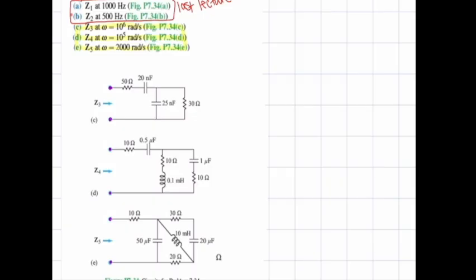Oh, okay. And in this case, your sources have to have the same frequency. They can have phase shifts on them, so they can be phase shifted between each other, but they have to have the same frequency. If you have different phase shifts, here you have no phase shift, and here you have a phase shift of -30 degrees. So these are the same frequency, but one's phase shifted relative to the other one.